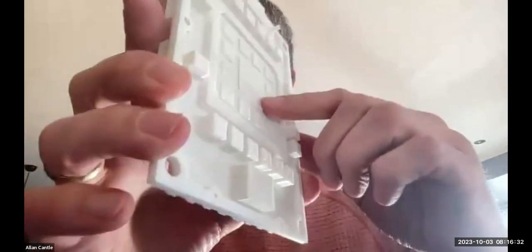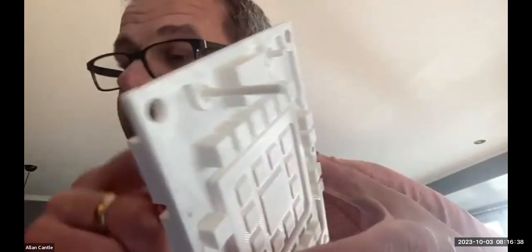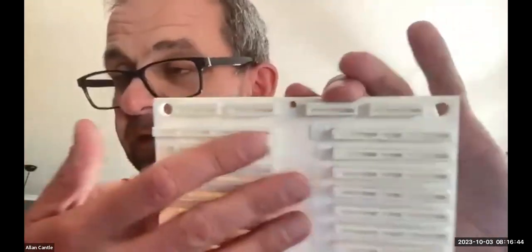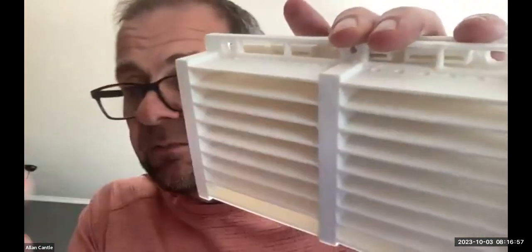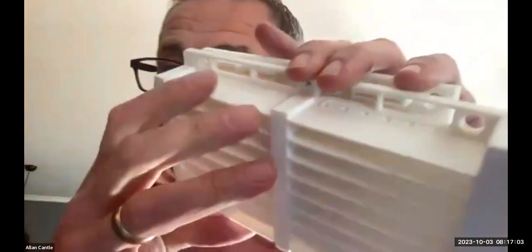So, you know, actually for Mick, our new chap, you can see that the connectors are directly underneath the processor chip. The big problem with the connectors is they invariably have mechanical strength pins that go through the board. So we need versions with no mechanical strength, all surface mount mating. And we would get the mechanical strength, and this is where we need some more mechanical expertise, from the actual cooling frame that goes around this. That will make sure the modules go in very perpendicularly, so they can't be torn off by a ham-fisted person inserting them incorrectly. So those are the tweaks that we need.